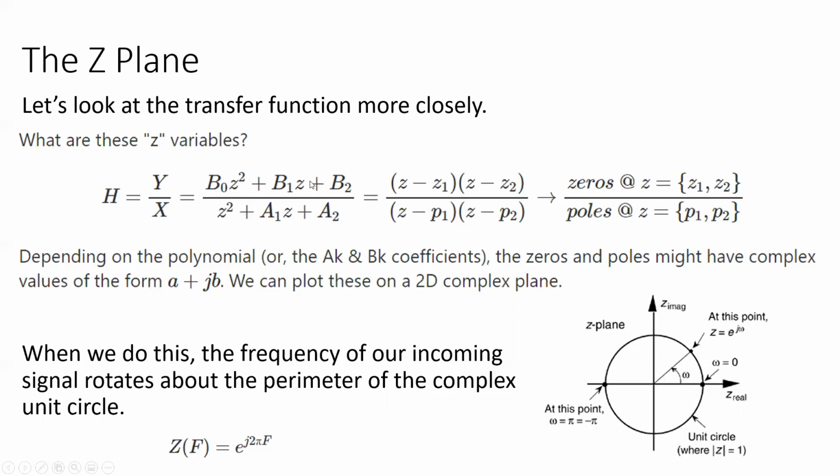If we factor on top and bottom, we can find where each of these, either the numerator or the denominator, would be 0. If the top equals 0, then the whole transfer function equals 0, so we call these zeros, conveniently. The bottom ones are called poles, and those are where this thing goes off to infinity if you happen to have your z equal to one of these.